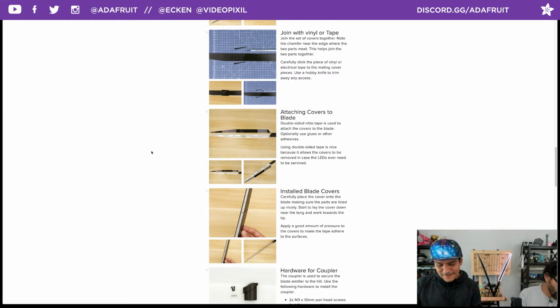But I wanted to. So Who Had 007 Adam is saying that you can just get a cheap smooth surface plate for the Ender 3. Yeah, like a PEI sheet, the spring-loaded, the magnetic sheets. We used glass, but you can definitely use the PEI sheet, and that'll give it a nice smooth finish. Make sure that your leveling is not digging into the bed. That'll avoid the rough finishes on the top as well. And to try out the ironing, that might work. Yeah, the ironing feature. Is it Prusa? It's Cura. Cura does it too. Yeah, I think they all do it.